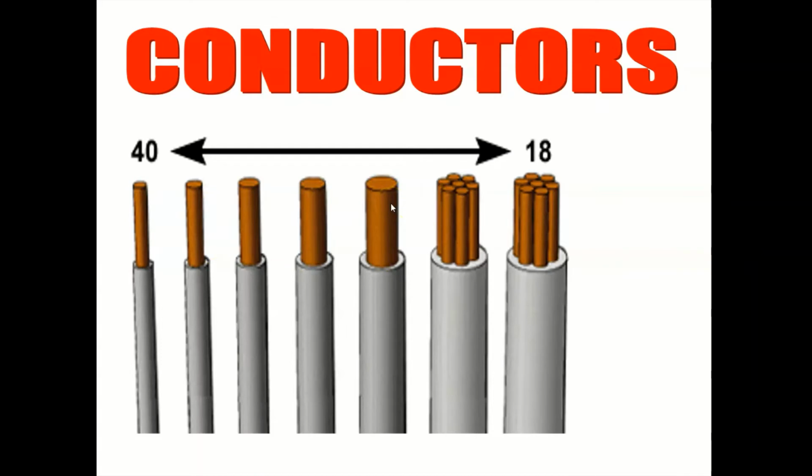The larger your wire gets, the easier it is to send current through it. But when you have really big wires like power lines that run hundreds of miles, they're not solid pieces of copper, even though the bigger this area is, the less resistance it offers. At some point, you get this weird thing called the skin effect, and essentially, all the charges travel on the outside of the copper wire.